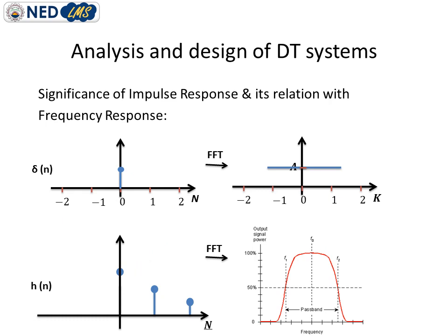What we need to do? We just need to take the fast Fourier transform or FFT of that particular impulse response, and the FFT of the impulse response actually gives the frequency response of the entire system.